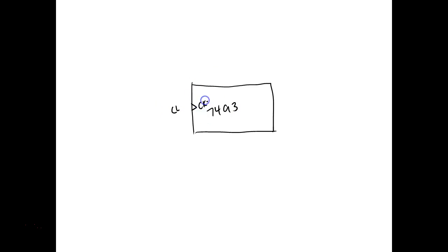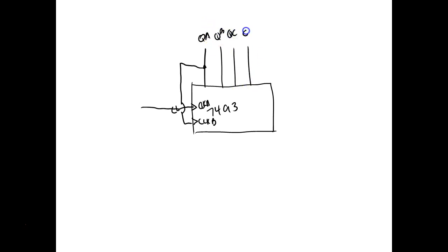Oops, this is clock A. And we're bringing our count into here, right? And we're taking the QA output and we'll feed it into clock B. So what are we taking over to our reset? Okay, so QB is fed into one of the resets. And what's the other one?